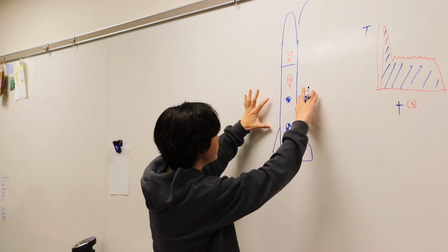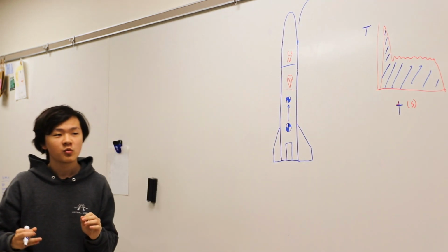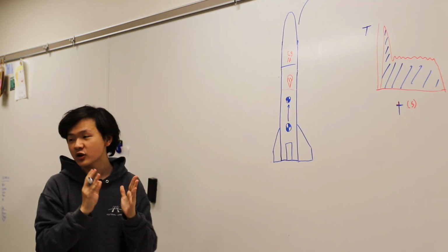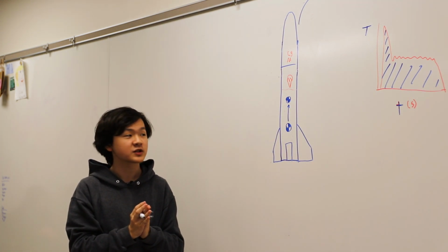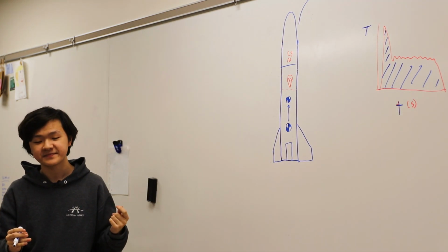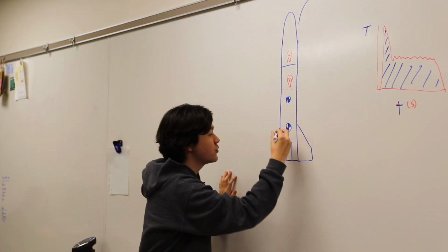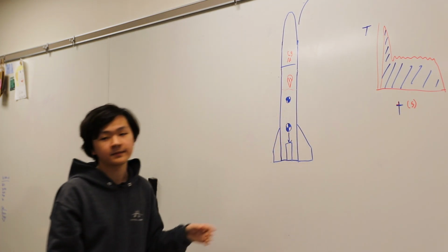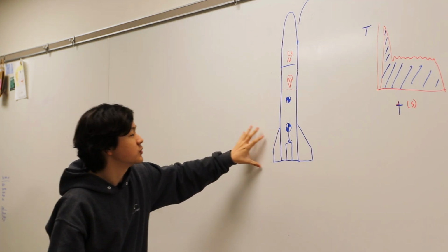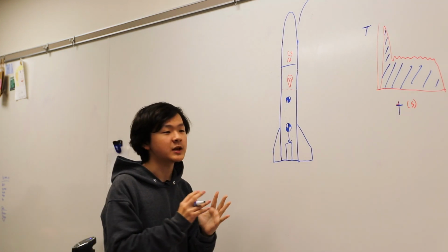We typically want it to be a medium ground, because if it's too close to the center of mass, the rocket becomes unstable because the correction of the rocket's course from the air becomes less substantial. But if it's too far away, the angular force that any pressure will exert on the rocket becomes too strong, and it becomes overstable.